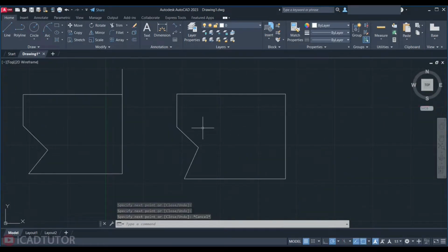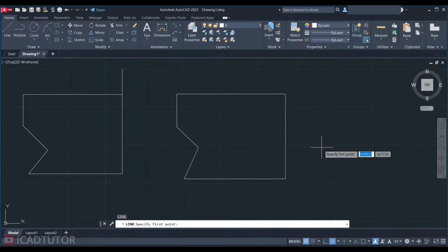Be sure to use it. Again, L, enter. I want to draw a line from here to the right so that the endpoint of this line and the midpoint of the above line be vertically aligned. If the object snap tracking is off, I must first draw a line using the midpoint enabled by the OSNAP. Also, if the OSNAP is off, let me press F3 to turn it off. In this case, it is not easy to find the midpoint. All these drawing aids make our job easier.